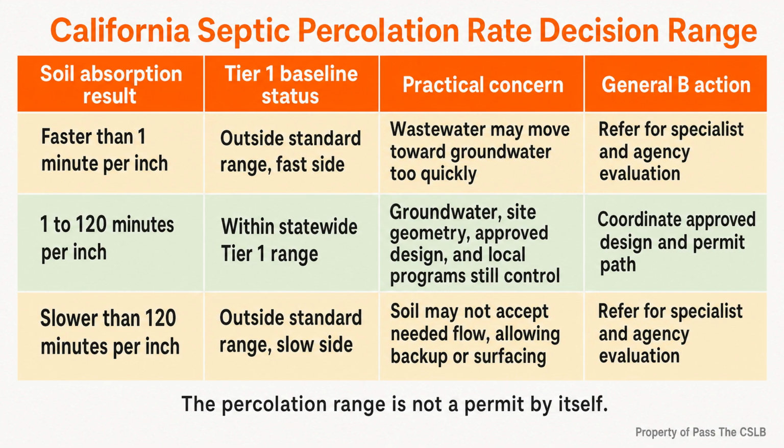Confirm which agency accepts the application. Confirm what site evaluation is required. Confirm who is qualified to prepare the design. Confirm when the inspection must occur before work is covered. Then build those dependencies into the schedule and estimate.